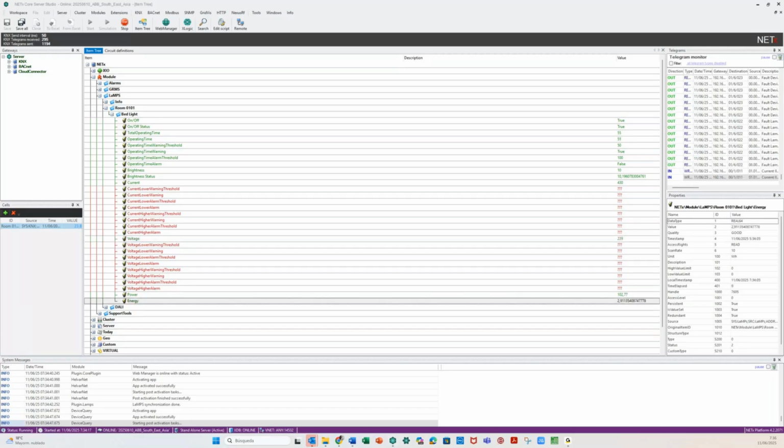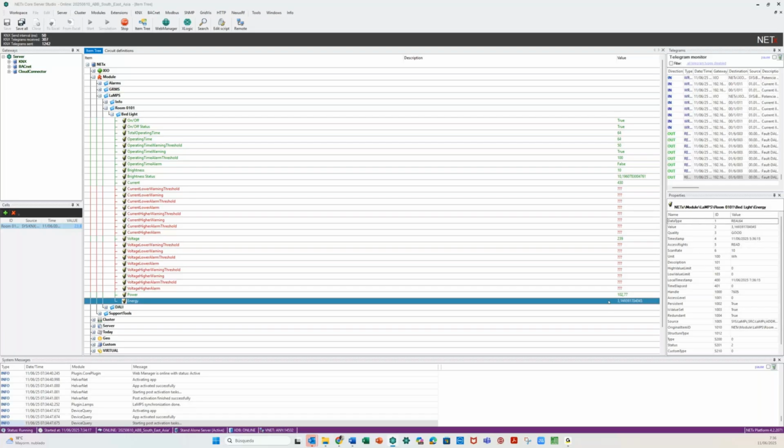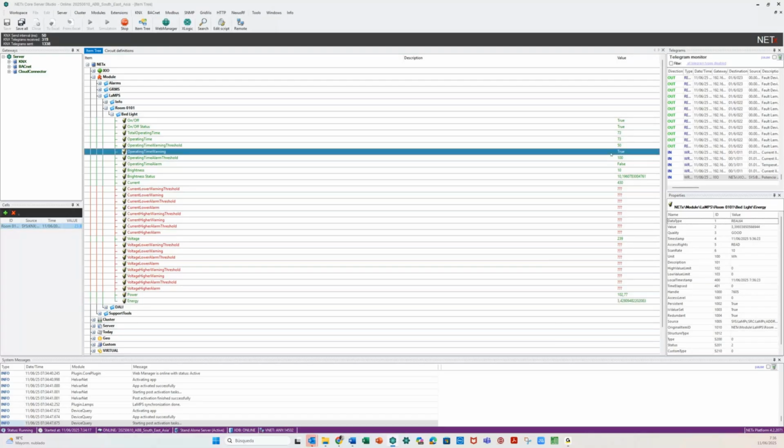So if you want this value to be used for the metering, it's okay. We can use this. It's an estimation of energy consumption, but it's valid for some calculations. So it's free for us. As you can see here, as mentioned before, this value is higher than the threshold for the warning. So the warning is now true. The alarm is false because the value is lower than 100.